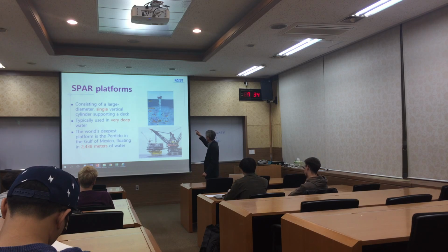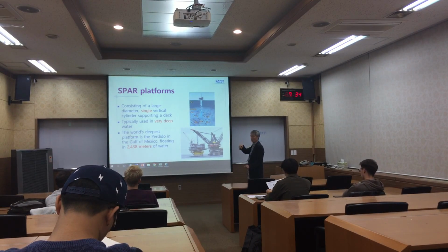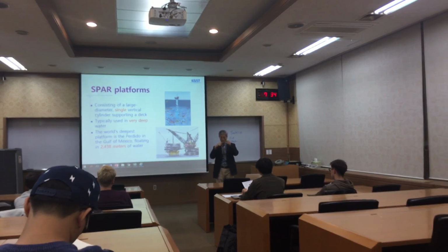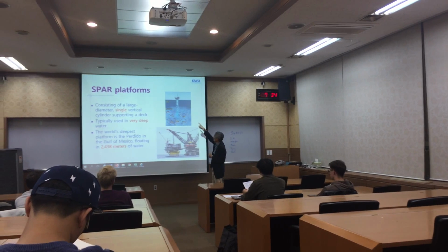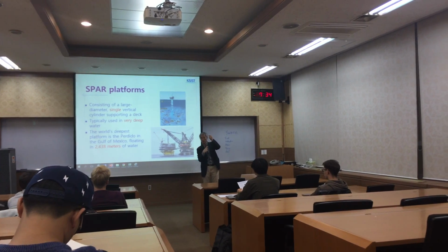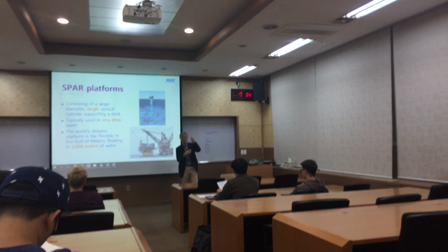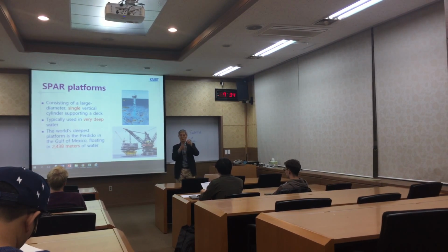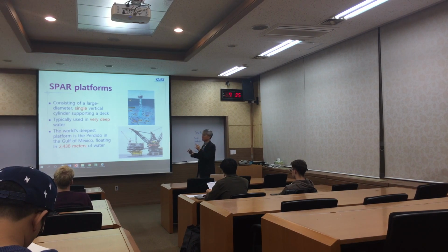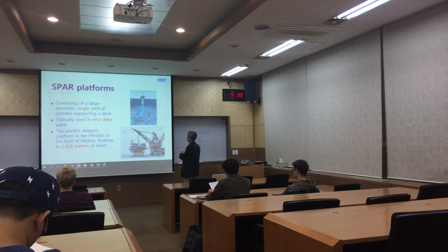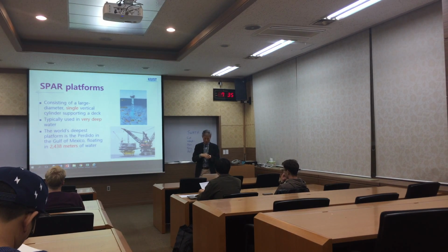One interesting portion of that spar is, how can I say, the rounding staircase, something that looks like a staircase in the spar type. There is a line along the cylinder, right? That is to reduce motion, to make resistance on motion. And also sometimes, because of tidal motion, they create vibration or motion. So they can be specially designed to reduce that kind of hydrodynamic forces.